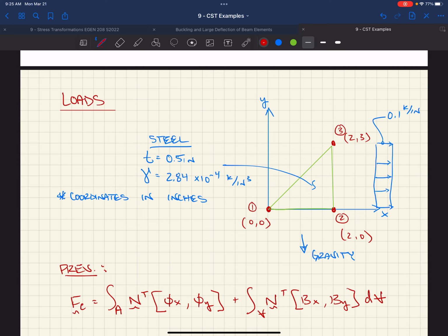Uplift. Uplift on one end. What about the other end? Compression. You're going to have these big T-C forces too, right? You might do T and C forces if, say, it was maybe a brace frame, because you have these big discrete boundary elements, we might call them. If it's a shear wall, like a concrete shear wall or a wood shear wall, we might want to linearly distribute that overturning force. So it'd look like the bending stress in a beam. We'd have the maximum stress on the ends, and then it'd be 0 in the center. That might be a little bit more accurate than just saying, okay, we've got this big overturning force, we're just going to have this big T and C force at the end.